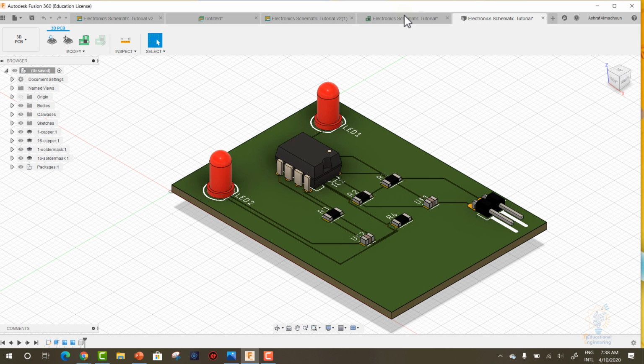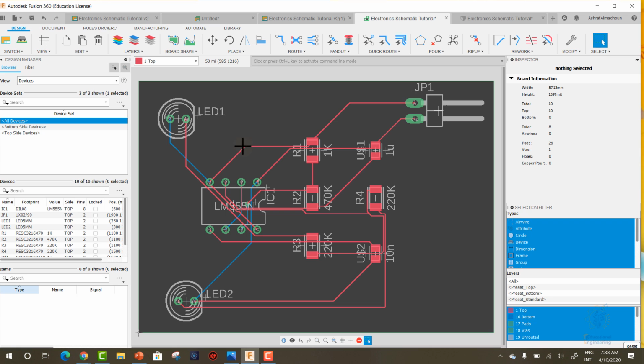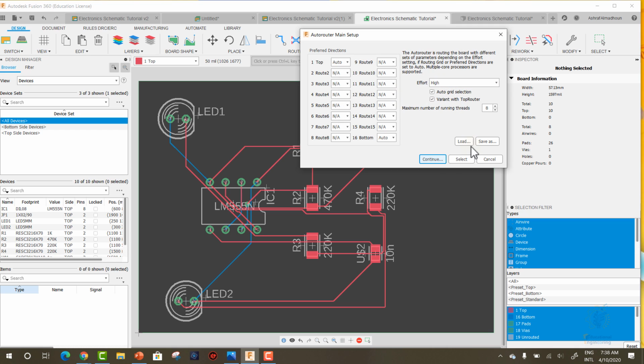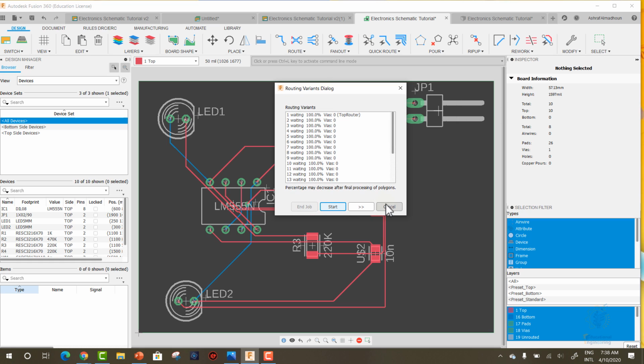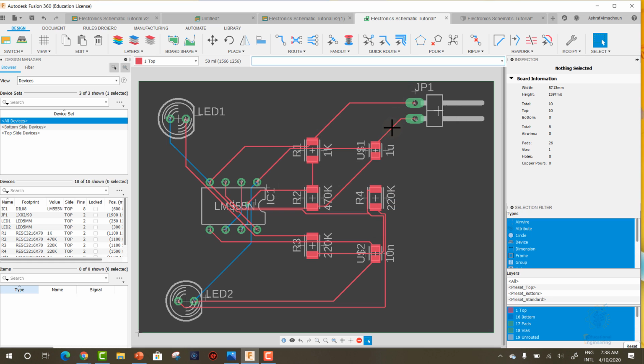And from there, you can move on to add different libraries, different items. You can change the auto route or route settings, and you can play with different aspects. Sometimes you can change the route width or you can simply remove all of these routes.